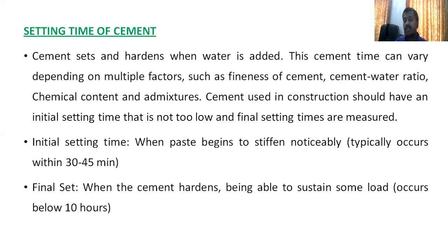So the setting time of cement is when cement sets and hardens once water is added. This time can vary depending upon multiple factors such as fineness of cement, water cement ratio, chemical content, and the admixtures. Fineness of cement, definitely yes. If the cement is finer, it will affect the setting time, because there is greater surface area. So in a good way it is going to affect.